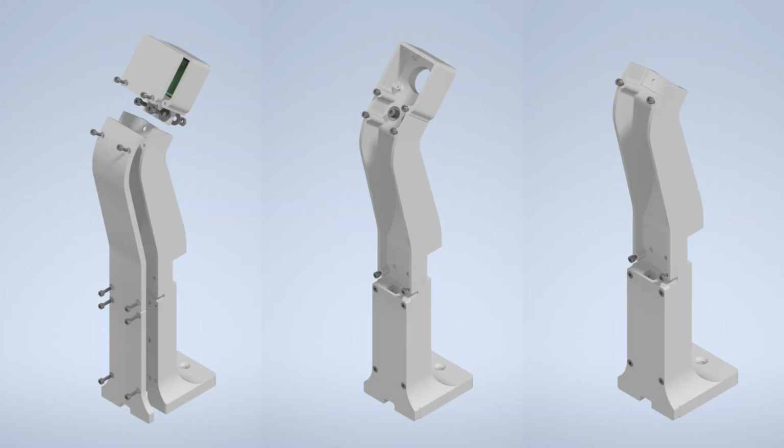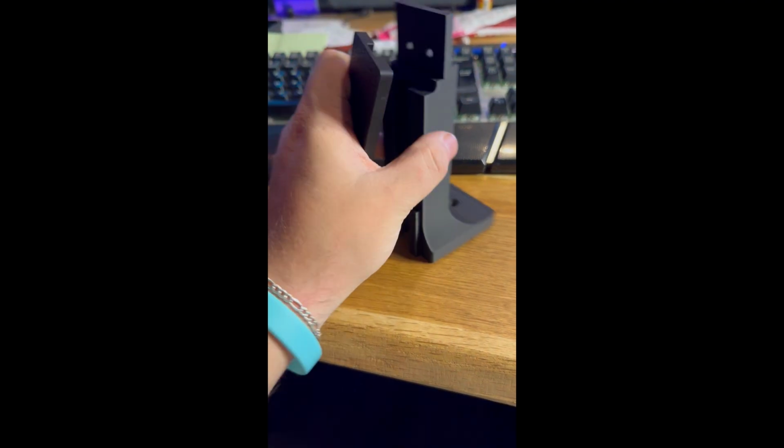So today I want to use the lid as an example. First, instead of using screws to fasten the cap, I will create a sliding mechanism so the cap can slide down from the top. Since the lid is always in the vertical position, I don't have to worry about the cap slipping off, so there's no need to lock it after sliding it in. So the result will look like this.